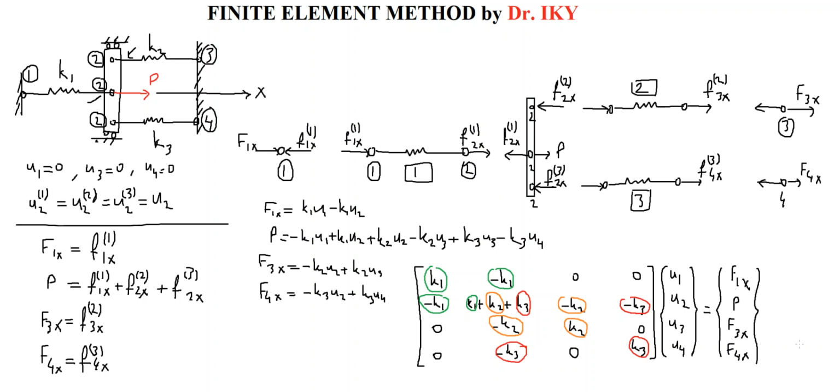If you want to solve for U2, we have already defined many techniques and you can apply them, especially starting with elimination. You will make some of the displacements, and considering those ones, the forces will be 0 by applying it to the rows and columns. And don't forget to apply the orthogonal start, and the end ones will be 1. So you will find the displacements. After finding them, you can add it into the displacement vector and make it equal to the force vector. So you will finally get the load values.